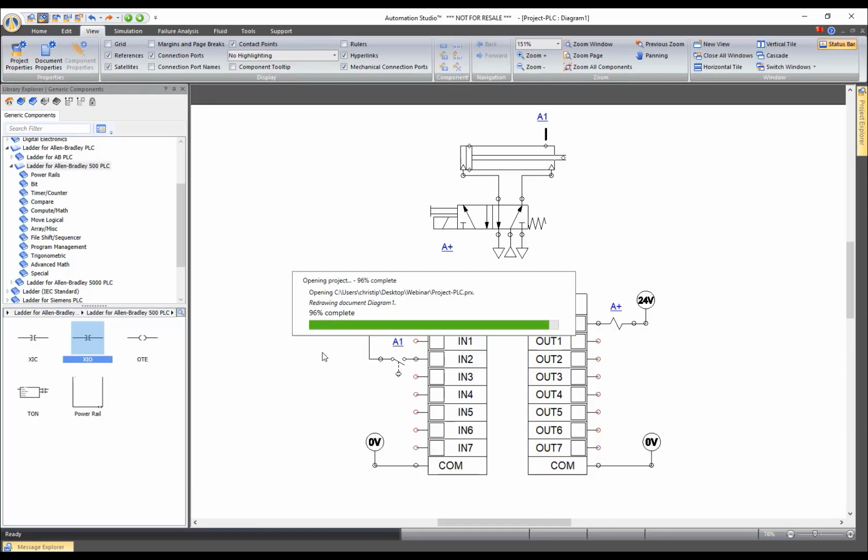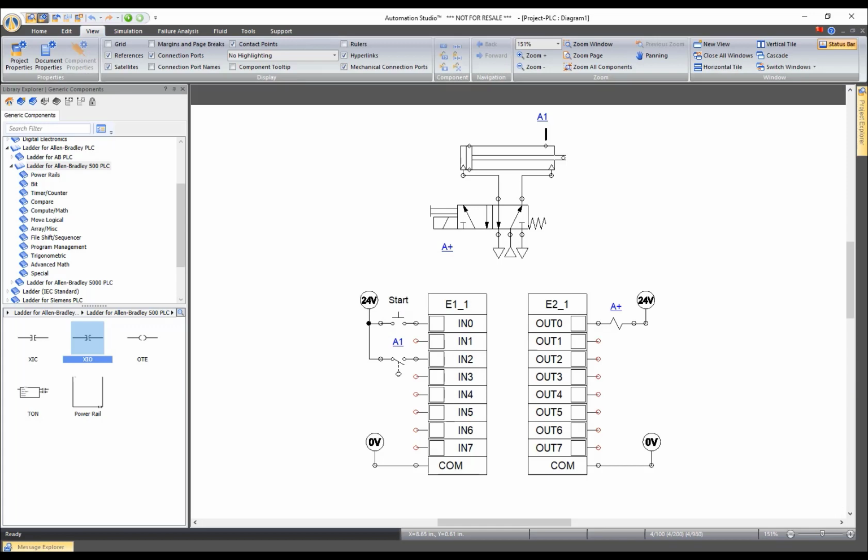We've developed these two modules, by the way, because we've had a lot of limitations with our old version. We could not write in the same variable, so we couldn't do a latch and unlatch. It was kind of like we need to use the two symbols that were combined together. It wasn't really like working with the real PLC.